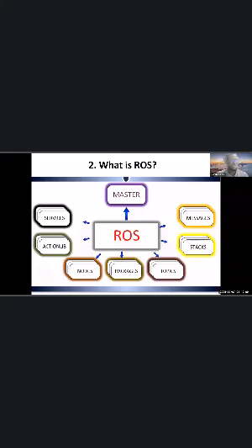I got this picture that explains what ROS is. This is actually ROS 1. In ROS 1, we use the ROS Master, but I will explain that term later. Then in ROS 2, we have DDS. I just wanted to explain some things in ROS, but as we move further, you will understand. In ROS, we have things called messages. I just wanted to point this out so that when you see them, it doesn't appear strange. Then we have what we call packages, ROS packages. Then we have nodes, libraries, services, and stacks.